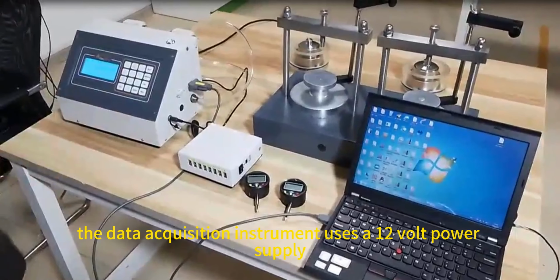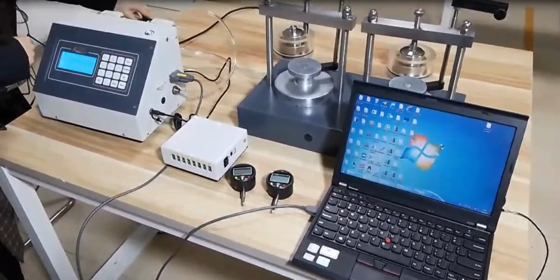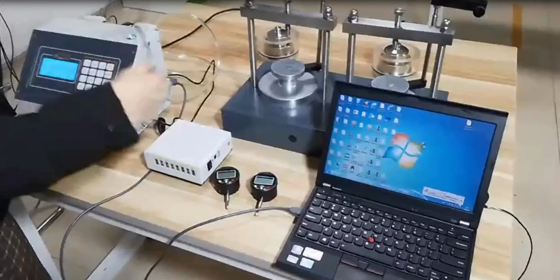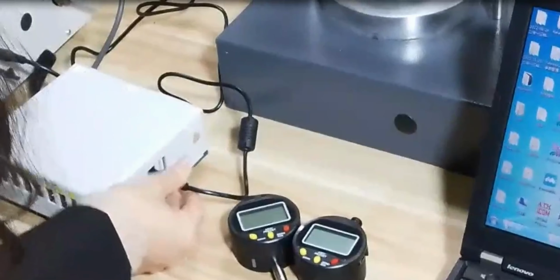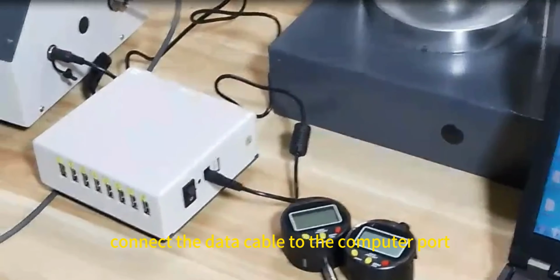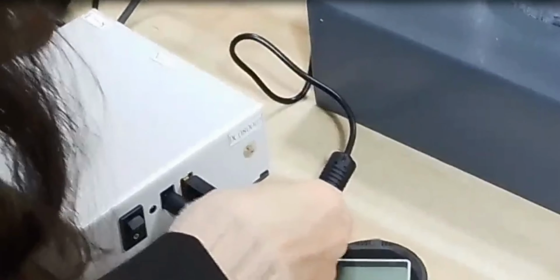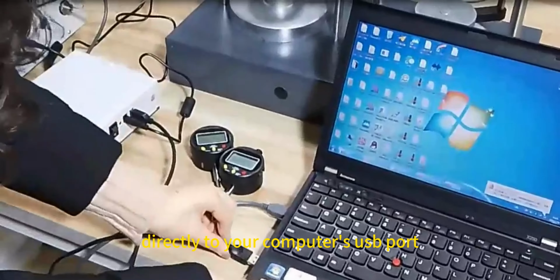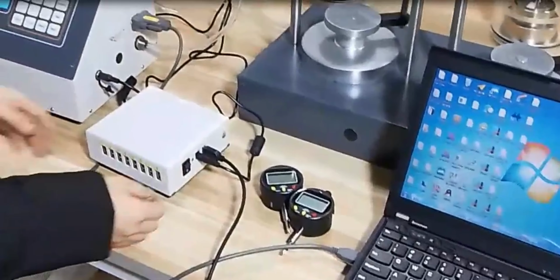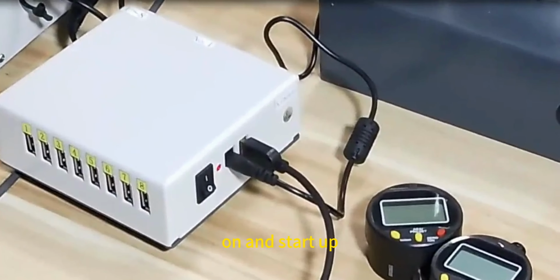The data acquisition instrument uses a 12-volt power supply. Connect the power cable to the power port. Connect the data cable to the computer port. The other end of the cable connects directly to your computer's USB port. Press the switch button and the light is on, indicating power on and startup.